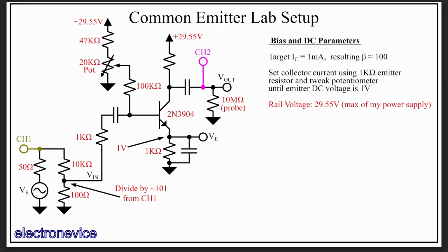easy to calculate. In order for our transistors to behave well in the forward active region, we don't want the collector-emitter voltage to get too low, so we'll decide we want a somewhat arbitrary value of 3 volts or larger, which is pretty solidly in the forward active region. So we want about 3 volts of collector-emitter voltage drop across the common emitter BJT.